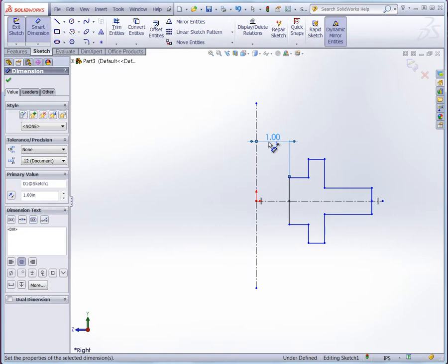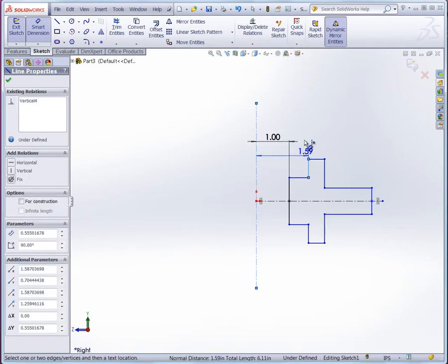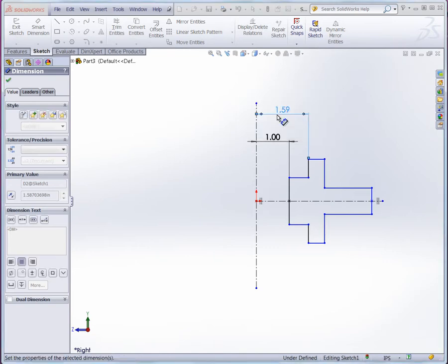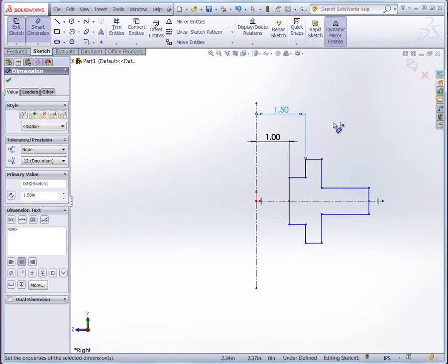The other thing is that I have a 4-inch outer diameter for that counterbore, and then the inner diameter there is 3, right? So this inner diameter here to the center line is going to be 3 divided by 2, which gives me 1.50.